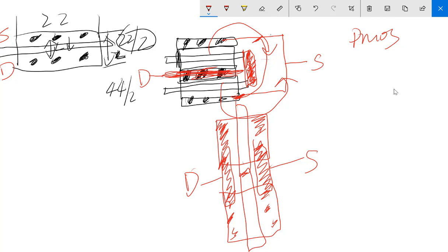So now it looks easier to understand because you didn't change the length at all, but you doubled the width of the transistor. So right here, this guy is equivalent to a 44 by 2 transistor. It's the same concept. When you combine 10 of them together, you are definitely getting a 220 by 2, right? It's the same concept.